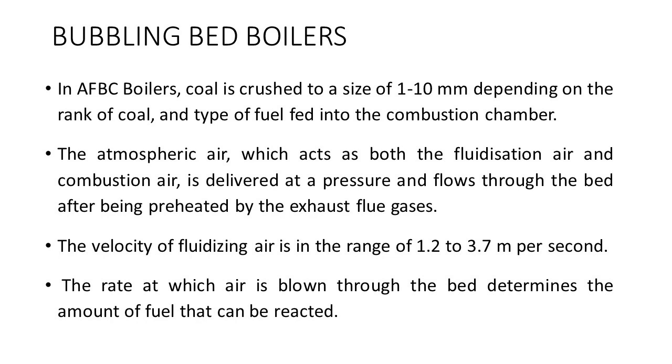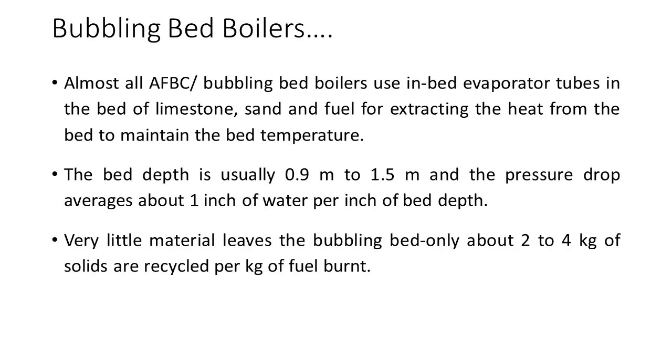The velocity of fluidizing air is in the range of 1.2 to 3.7 meters per second. The rate at which air is blown through the bed determines the amount of fuel that can be reacted. Almost all AFBC bubbling bed boilers use in-bed evaporator tubes in the bed of limestone, sand and fuel for extracting the heat from the bed to maintain the bed temperature.